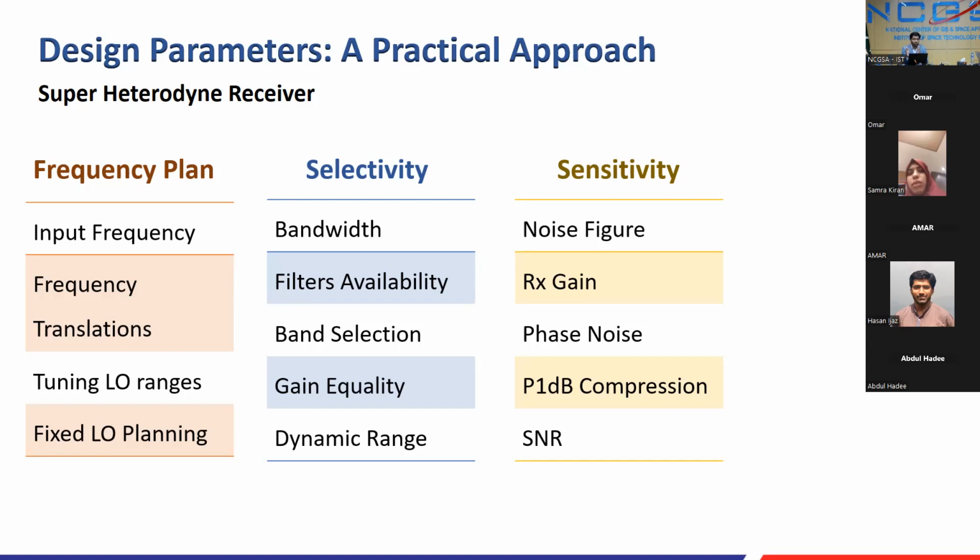And when the harmonics increase, then you have two signals. You are feeding two signals to your system, and there will be mixing products, and you won't be able to resolve your IF or frequencies at a later stage. So that is the significance of P1 dB compression, but we will come to that later as well.